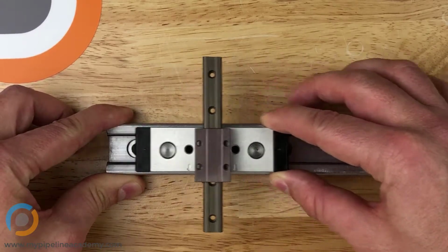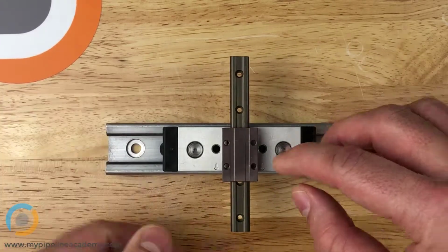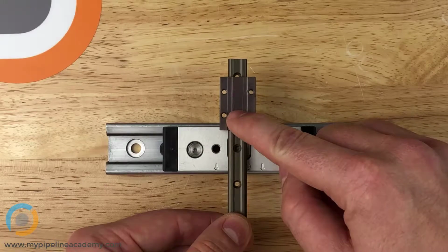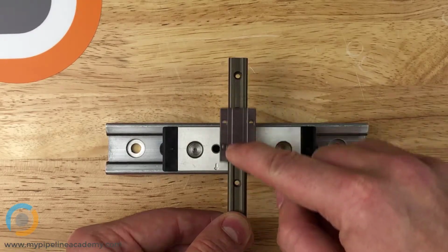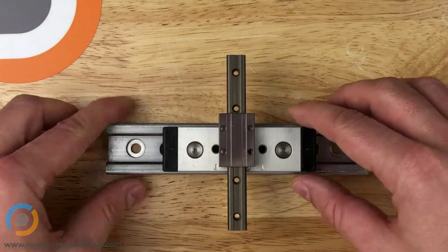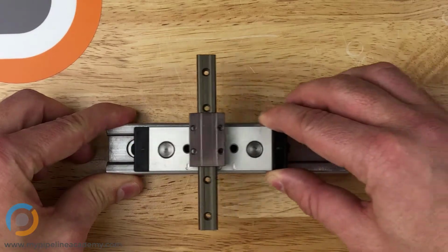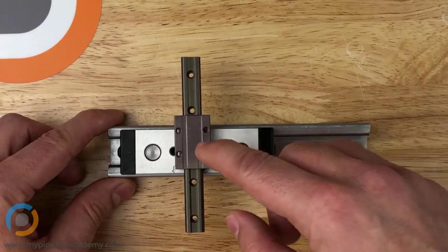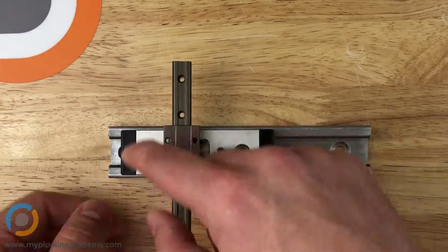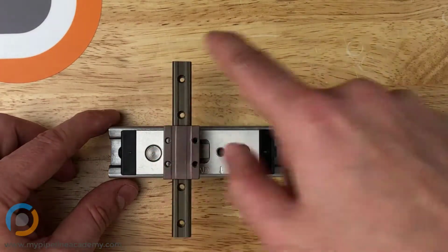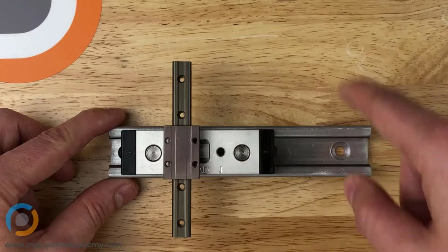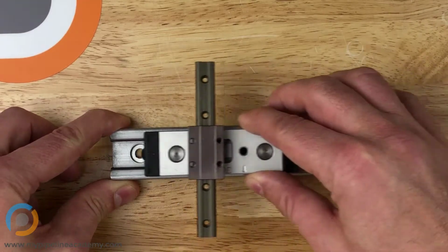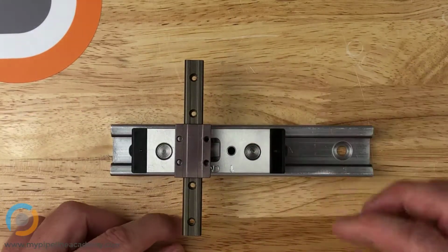So we have our X carriage moving back and forth like that, and then we have our Y carriage moving back and forth like that. And this is actually something that's done commonly, mounting two rails and carriages to each other, to achieve any position in an X and Y plane, any coordinate you can achieve with two rails and carriages mounted to each other like that.